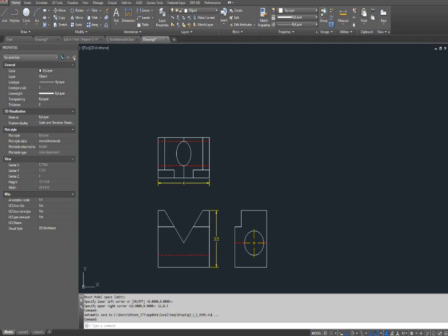In AutoCAD, we plot, we don't print. So like in MS Word, you type a document, you're going to print that when you're done. If you're online, you're going to print that when you're done, but in here, we're going to plot. So I'm going to use that command. Here we go, plot.